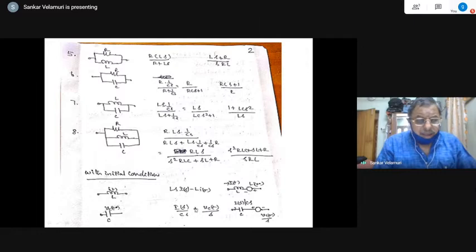So similarly, the voltage, this is Is by Cs plus Vc0 minus by s. So this is again opposing this, but it will be in series with this, the current that is taken between the terminals, because Is is always in the direction of the current, there will be a potential drop. So plus and minus here. Therefore these voltages will be aiding with respect to each other, whereas the voltage across the inductance will be opposing with respect to each other.